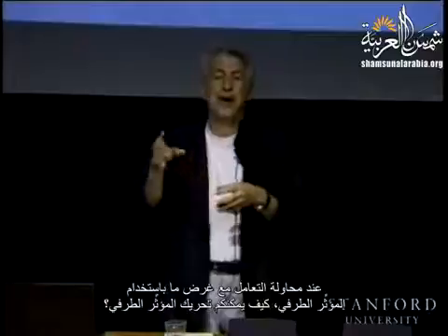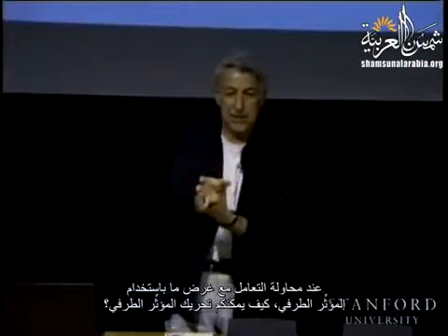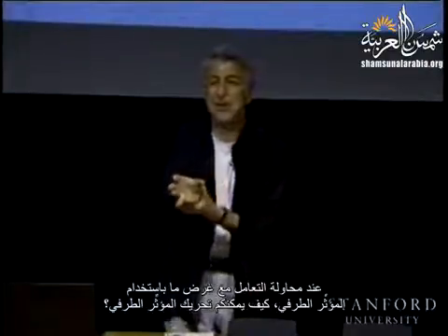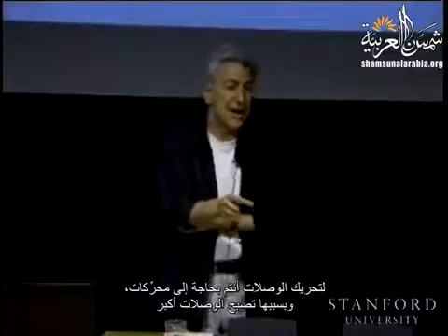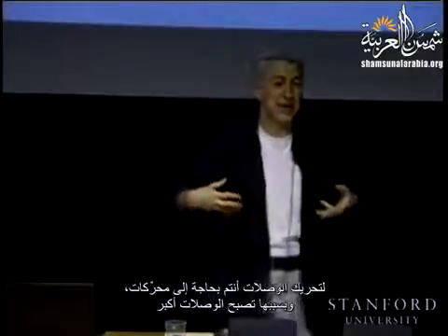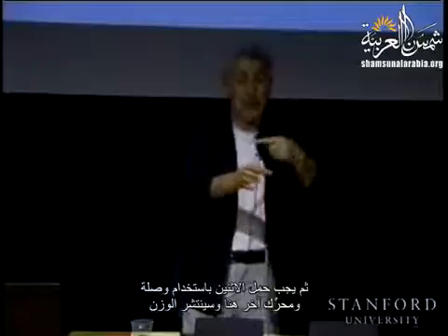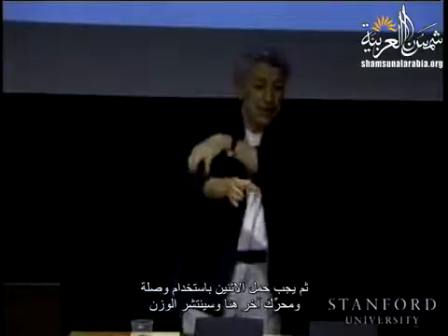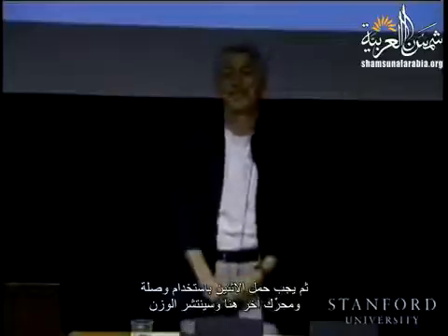And you can see it every time. You are trying to manipulate an object with this end effector. How do you move this end effector? You need links. And everything we were studying was the carrier of this end effector, right? And to actuate your links, you need motors. And because of the motors, your links become bigger and bigger. Because you put this motor here to carry this end effector, then you need to carry both with the link with another motor here, and you propagate the weight.